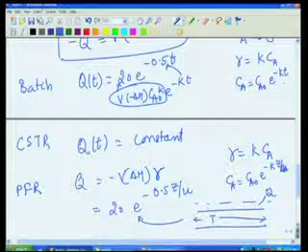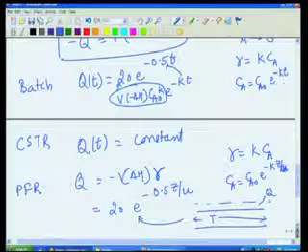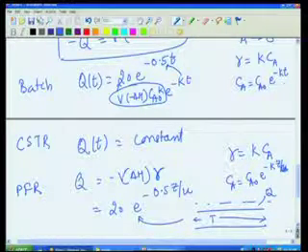How do you achieve that? You will either have to change, what? The reference temperature along the length of the reactor, not an easy task to do. You will have to do something so that the rate of heat added or removed is exponential. So, as I said, maintaining isothermal conditions, even though easier said on paper, is very difficult in practice, particularly for a tubular reactor. How do you do that? Because you have to change your heating or cooling rate along the length of the reactor.